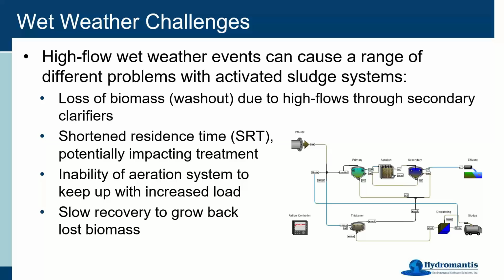And if you do lose your biomass, or there is something that's happened and there's a loss of performance, you may find, of course, that it takes a while to grow back all that biomass, depending on what kind of system you have and what kind of biomass makeup you have in your activated sludge. You may find that could take quite some time, you know, days or weeks.